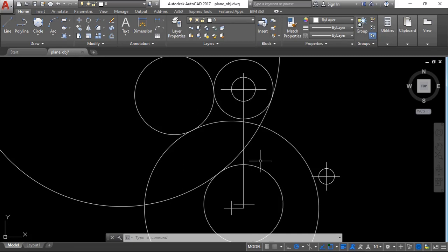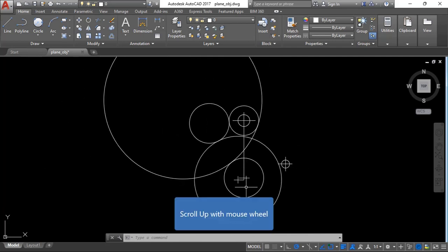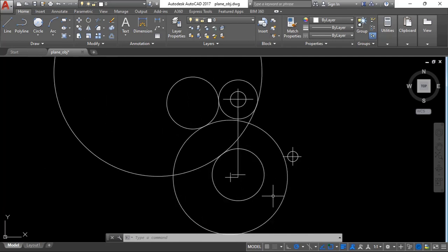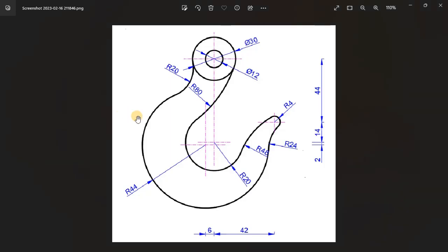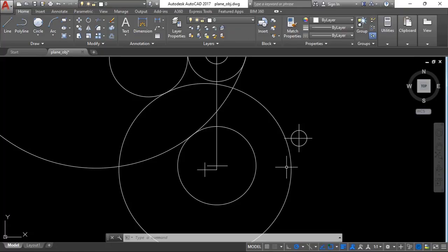Yeah, so in order to get rid of the unwanted bits, of course you know what we use is the trim tool. So same thing with this, we are using the same. So we have radius 48 and radius 24. Okay, so same idea with that one of radius 48, same idea as the previous example.